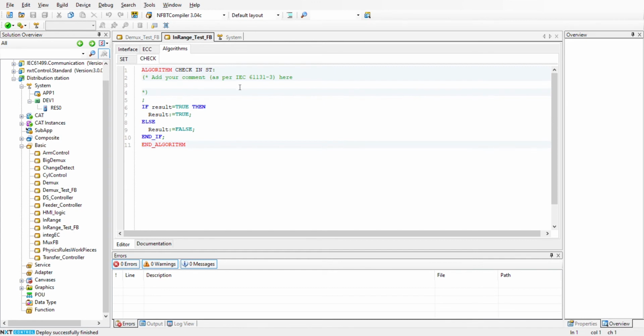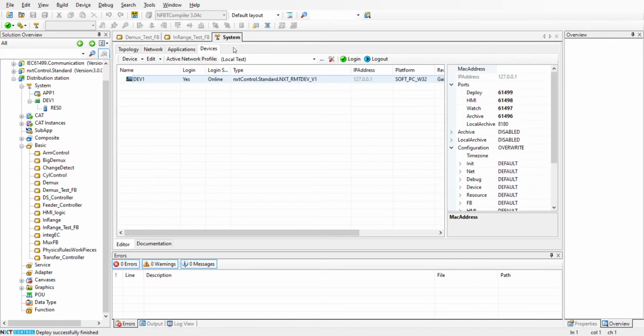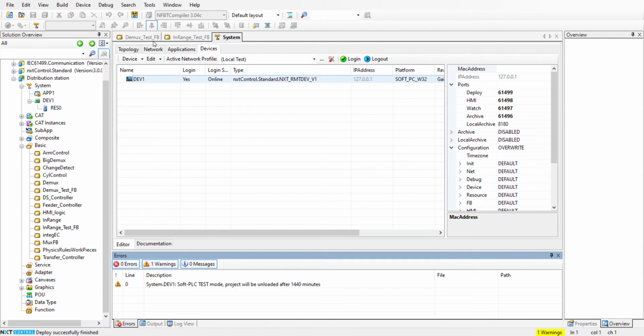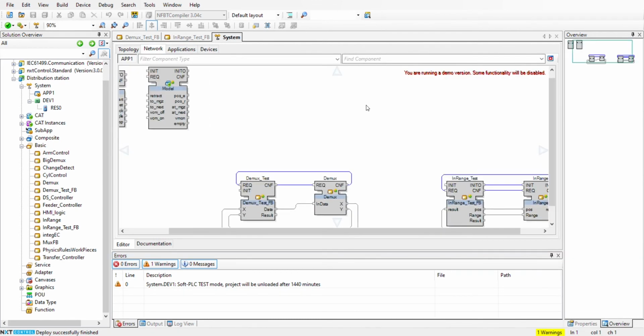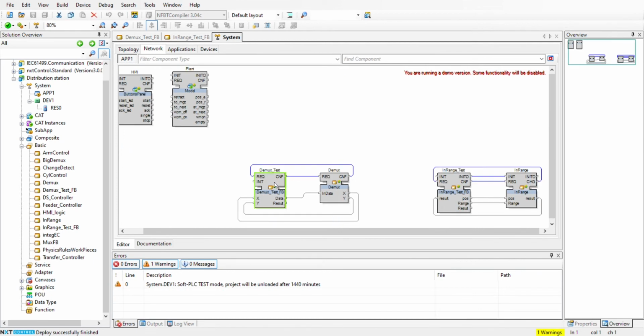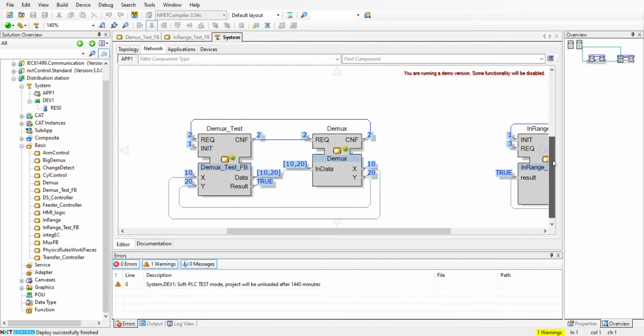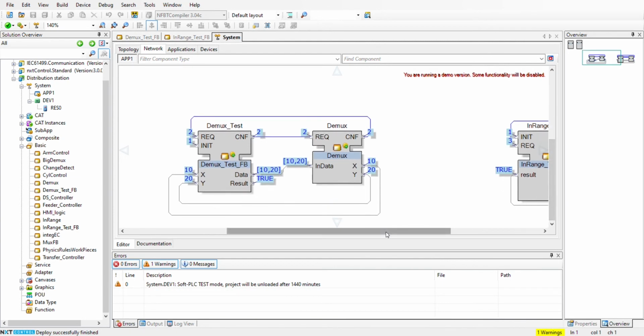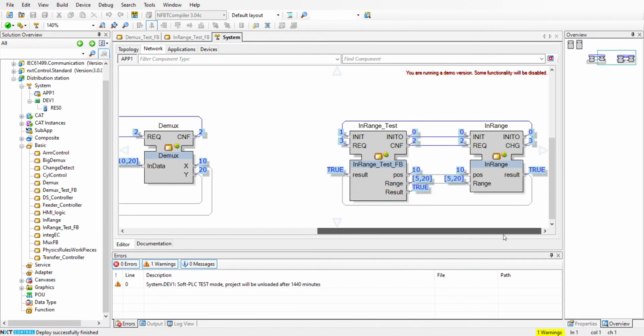The control logic of controllers also can be tested by adding an additional test functional block. The control logic to detect deadlock using an additional functional block can be implemented by converting deadlock detection algorithms to control logic, execution control chart. Design and verification in deadlock detection for connected controllers are more complicated and difficult to implement as an additional functional block. Path identification and counterexample generation for deadlock detection in concurrent system implementation can be developed using NuSMV.